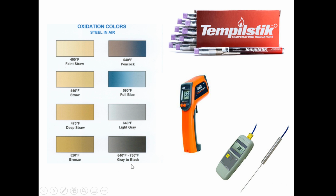Now, I threw this little table in here to remember something, because I already said straw color. I was talking about color. I shine up that chisel and I bring it up to temperature using straw as the color for my goal. Now, if I get this right, I'll get about 400 degrees, and I will. Now, this is important. I'm going to lose a little bit of Rockwell. I might lose 2 or 3, maybe up to 5 Rockwell by doing this. But the longevity and the lifespan of this joint just went up exponentially. So we need to consider that.